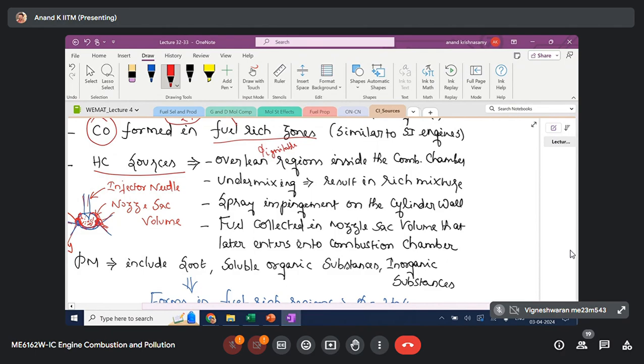So there is a range of phi for fuel-air mixtures that you can burn, that you can ignite. What will happen due to over mixing? There will be regions that are very lean, in the sense of too much air and very little fuel concentration. It is below the lean flammability limit of the phi value for the given hydrocarbon-air mixture. That's why you will have unburned hydrocarbon formed with those mixtures. There is no complete oxidation because it is below the lean flammability limit. There may be partial oxidation leading to forming HC.